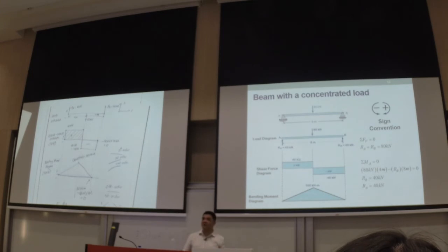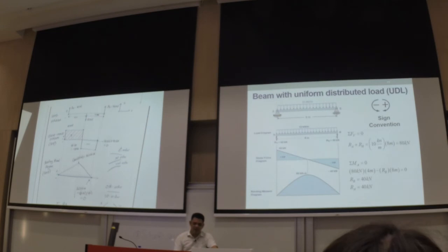Okay, so we study by block. The magnitude of this one will be based on the area above. Of course, starting with this point here. So we move by order. So as we go down, load diagram, shear force diagram, beam moment diagram, the order increases. So this is what we have here, to be able to get the reaction forces.